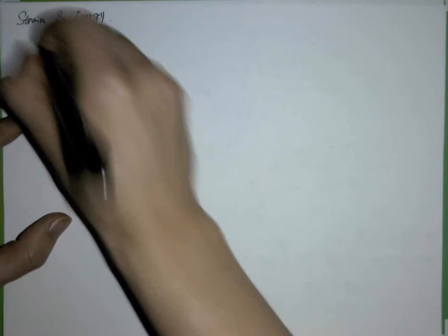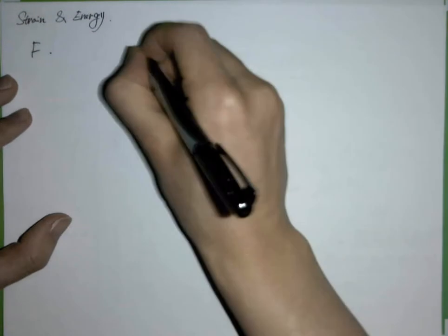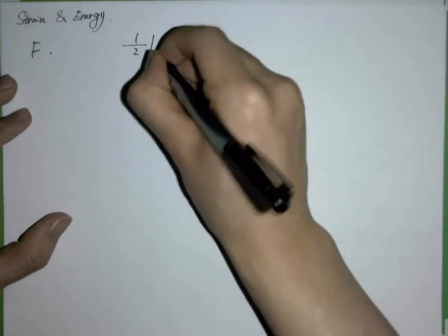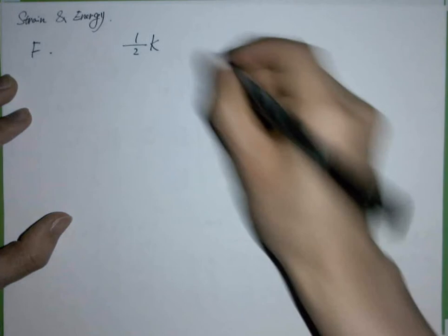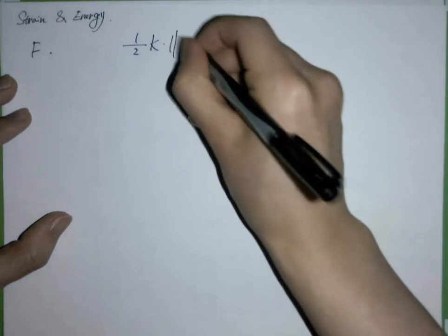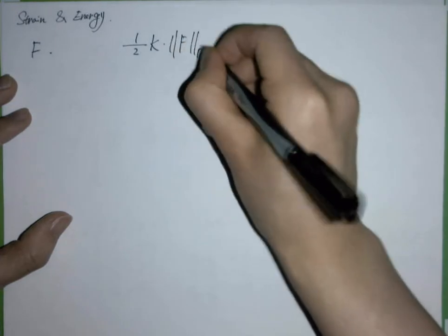The most straightforward one, if you want to take an analogy of a mass spring system: how about we measure the strain as the deformation gradient itself? And then the energy will be something like 1/2 multiplied by a constant stiffness multiplied by the Frobenius norm of my deformation gradient squared.